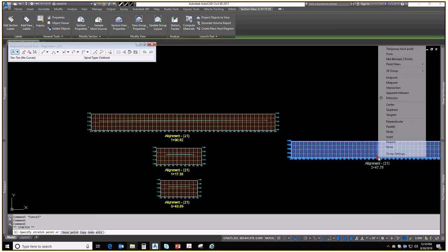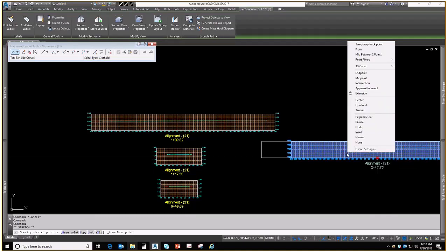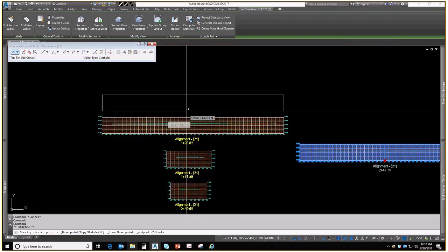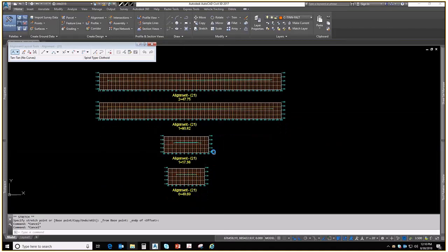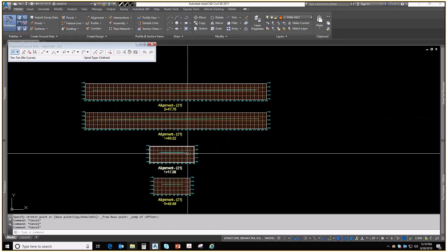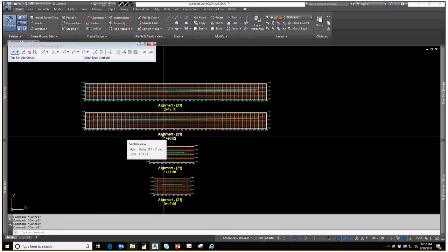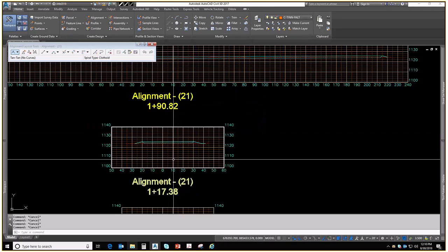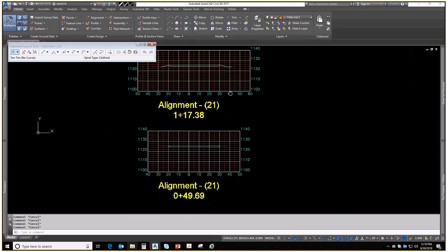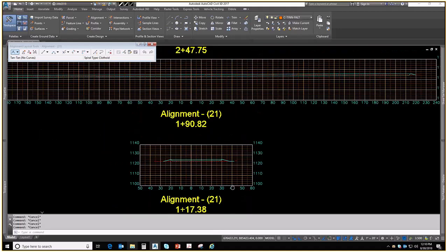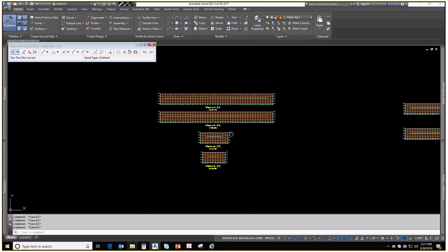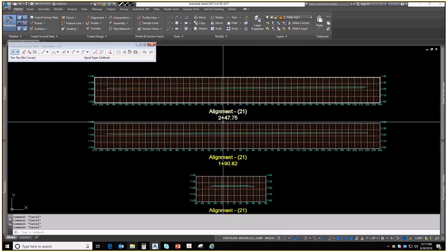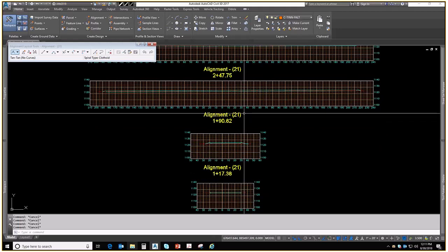The other good thing about putting earthwork sections on the plans, it's amazing how it inspires a sense of accuracy on your earthwork sections when you know they're going on a set of plans that's going to be sealed. So it kind of takes the sloppiness factor out of cutting earthwork sections and saying good enough, because you really have to check them and refine them if they're going into your final product that goes to the client, to contractors.